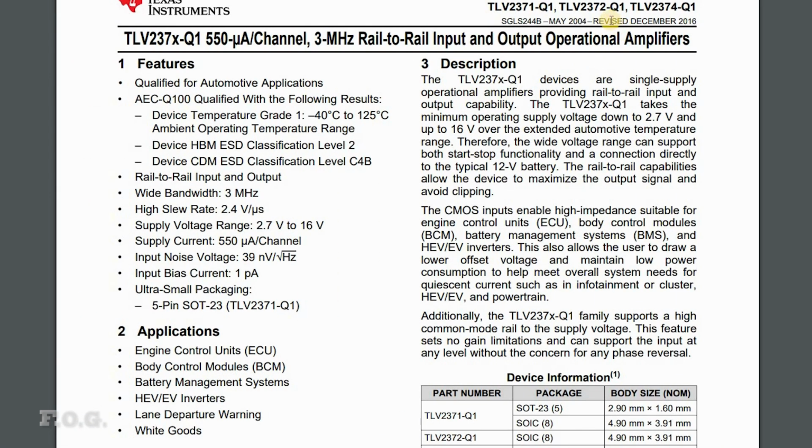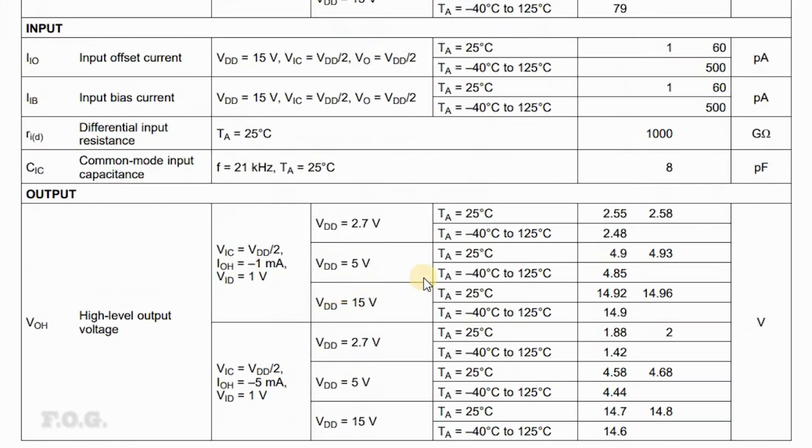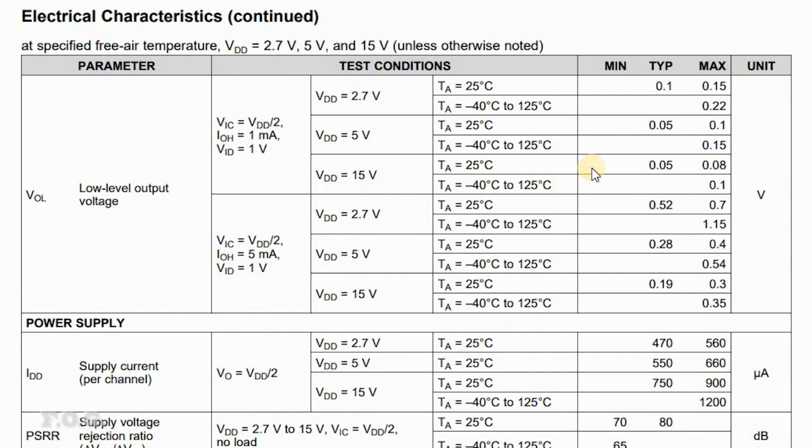Thankfully, there are now newer generation op amps out there, such as the TLV2372, I think, which I bought recently, the output of which can swing pretty closely to the supply rails, under 100 millivolts, I believe. Now to be honest, losing a little bit of range at the top end of the current measurement scale is likely not going to cause you much of a problem. But at the lower end of the scale, if you want to measure those very small currents, even losing 100 millivolts could be a big problem for your application.